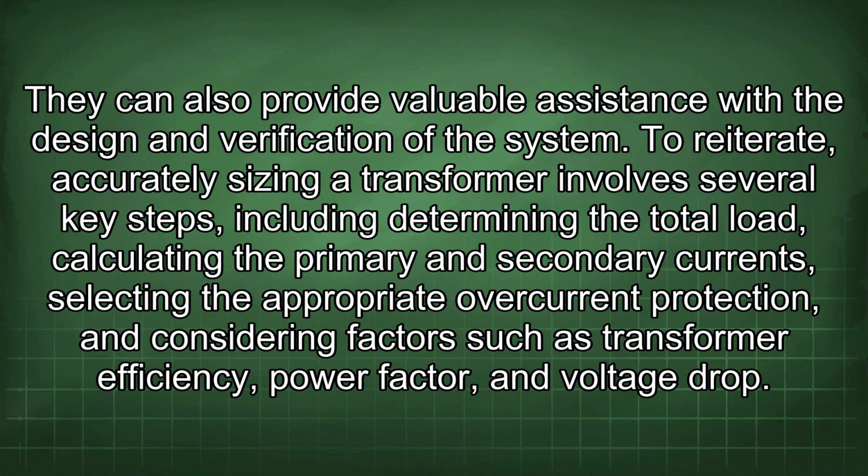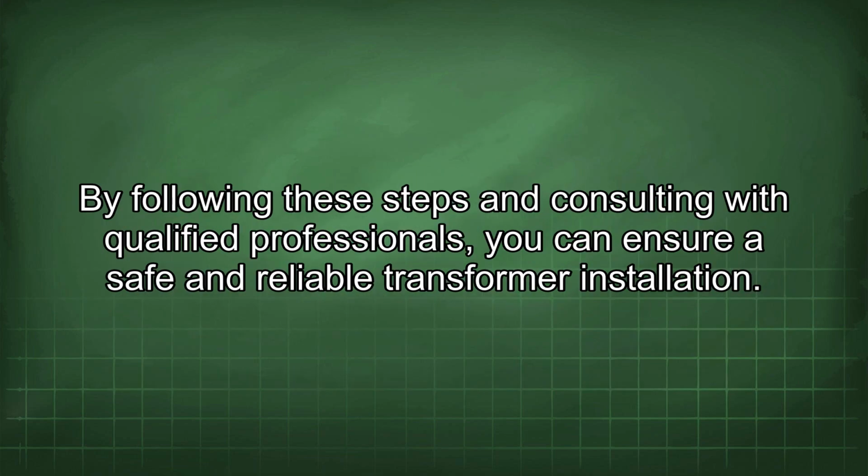To reiterate, accurately sizing a transformer involves several key steps, including determining the total load, calculating the primary and secondary currents, selecting the appropriate overcurrent protection, and considering factors such as transformer efficiency, power factor, and voltage drop. By following these steps and consulting with qualified professionals, you can ensure a safe and reliable transformer installation.